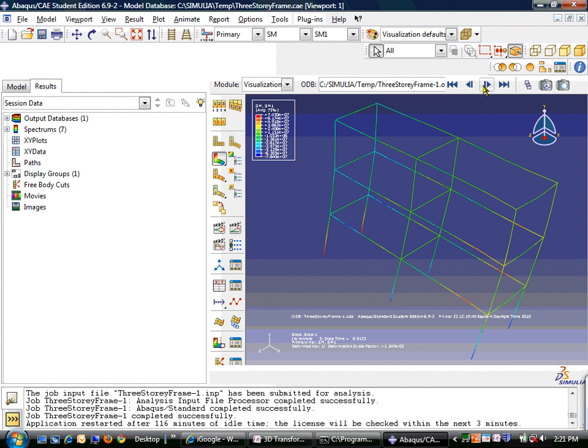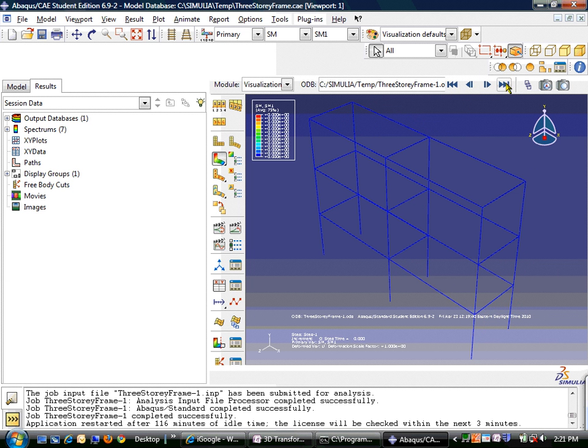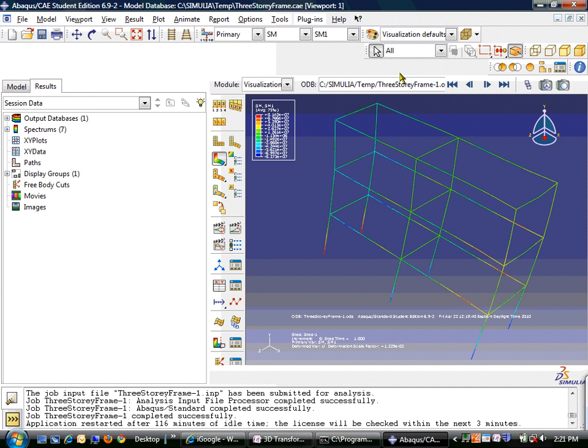Basically, this is the original position. This is the deformed position under those loads, and you can go and find out what is the section force, which is actually the shear force at any location within the beam, and section moment, which is bending moment at any location in the beam, and then you can use that to design your structure, individual beams and columns. So usually it's not that difficult, and you can see all these individual beam elements right here. In this case, I've used 5 beam elements along the length of the beam.